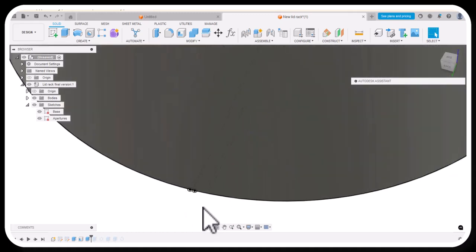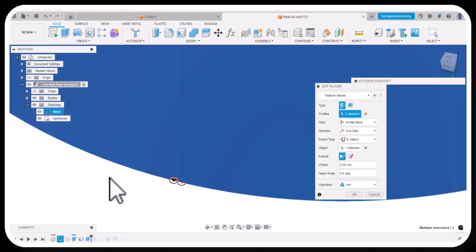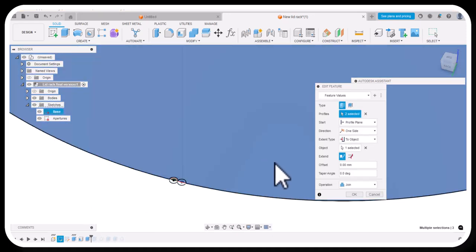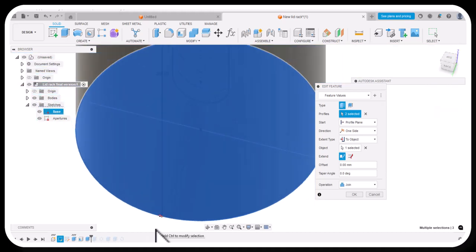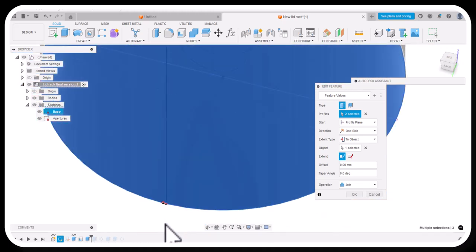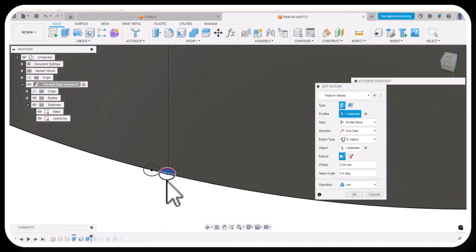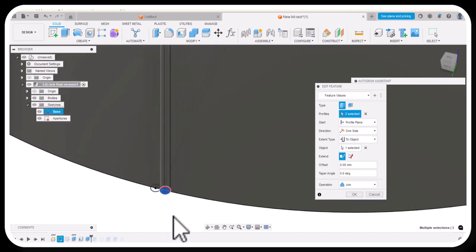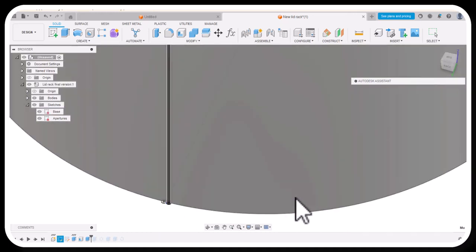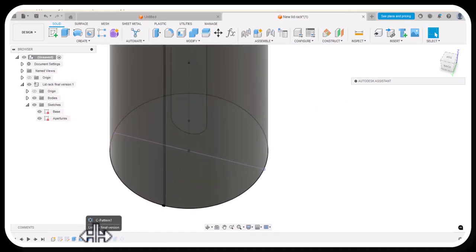Okay, so we're extruding this circle down here. Remember, we moved those two circles, so I'm going to edit that feature. But notice it's highlighting this entire blue area back here. And if I finish sketch, it's filled that back in again. So I'm going to control unselect that area. And so I only want this area and this area out here. I'll control select that area. That gives me that rib. Okay. And then I'll go to the next one.